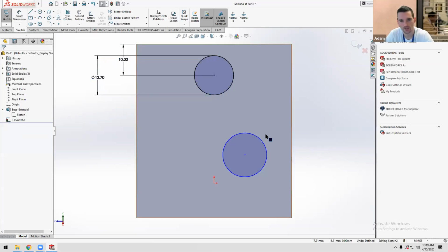Then let's hit escape and let's dimension a circle based on another circle. But maybe there's a weird angle that it's related to the circle width, right? So maybe I can't really dimension it straight off of any edge. So I'm going to use a construction line there. That helps me position things exactly how I want. I can get to that in this line tool, which shows this dotted line.